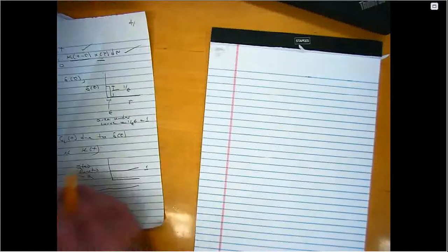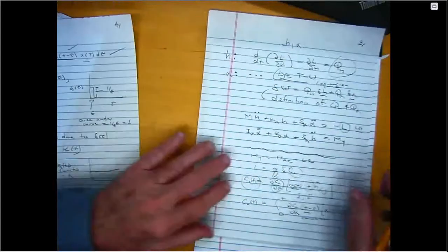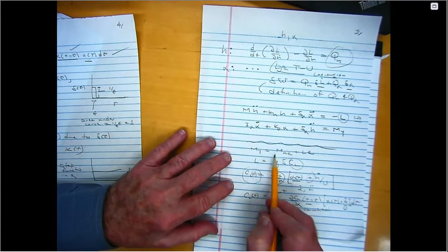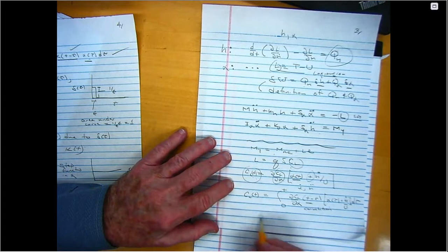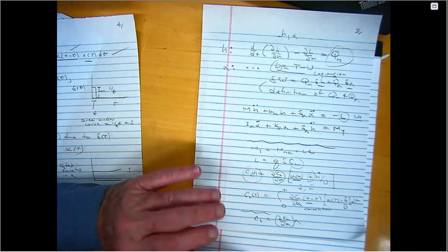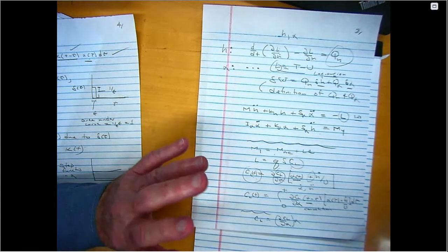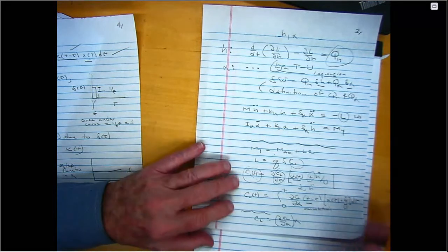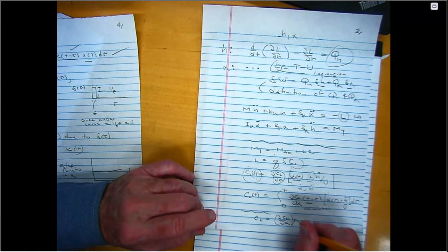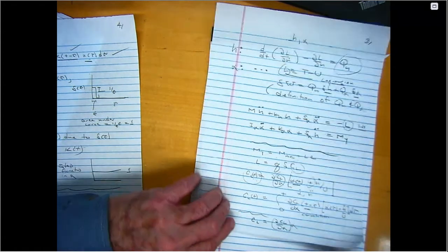Okay. So let me go back to here, just to remind you of what we have. Here are our equations of motion. Here's our moment. Here's our lift. And the simplest possible lift is dL is dCL/dalpha times alpha. No h at all, no h dot, no alpha dot, just this. Is this a reasonable thing to do? It turns out it is if the frequency is really small. How small? I'm glad you asked.